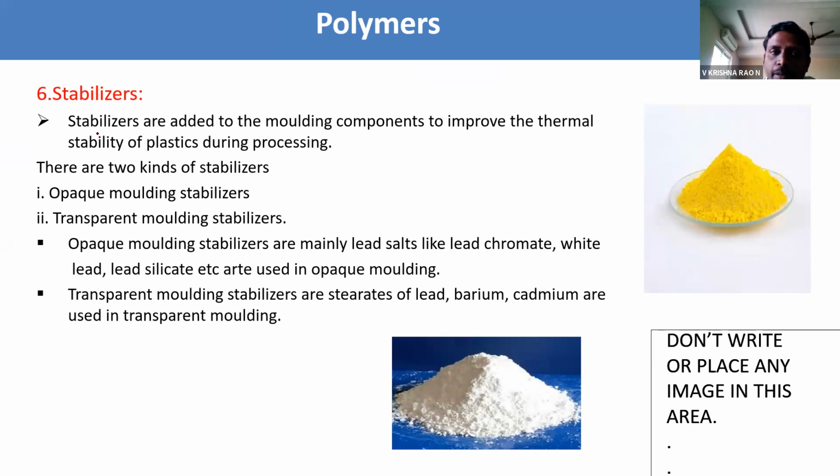Next, coming to the stabilizers. They give stability to the plastic during processing. Stabilizers are added to molding components to improve the thermal stability of the plastic during the processing.